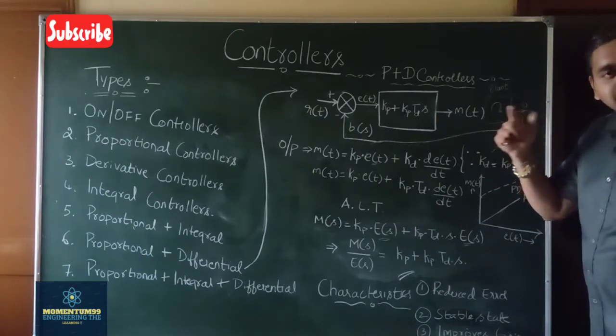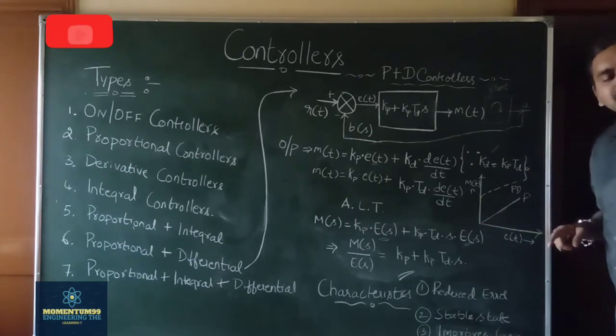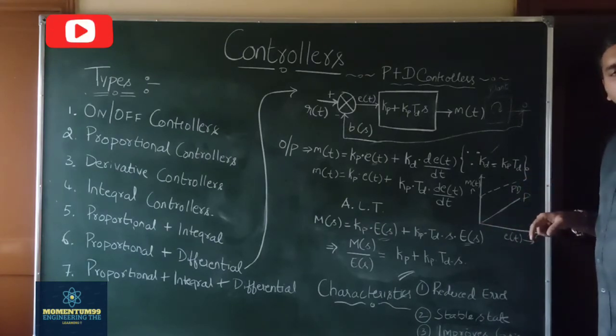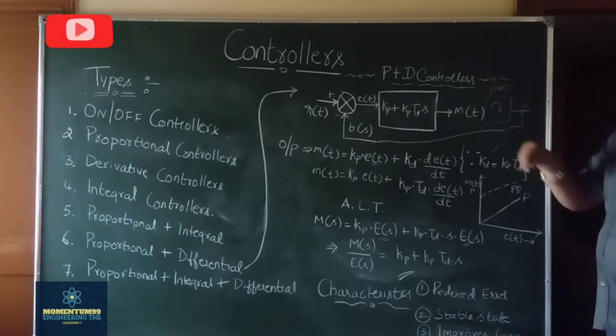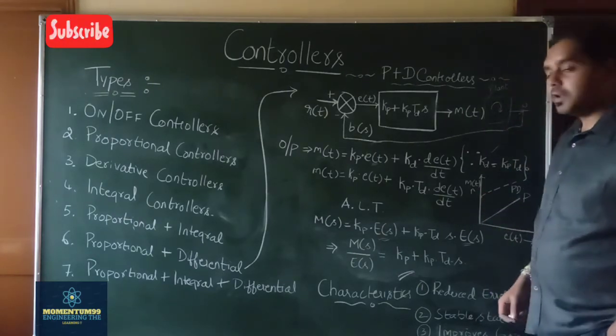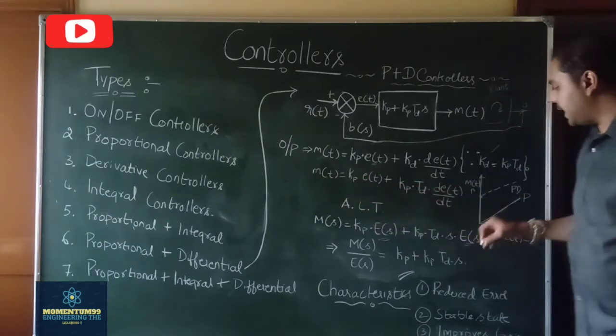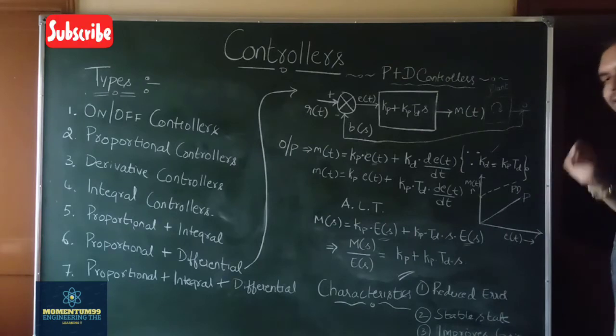It improves that ratio. Now moving on, we have a graph here which shows the relationship between the output and input of the system in the case of both the proportional and the differential controller individually. In the case of proportional control, we know that the output is proportional to the error input signal, so we will have a straight linear graph like this one.